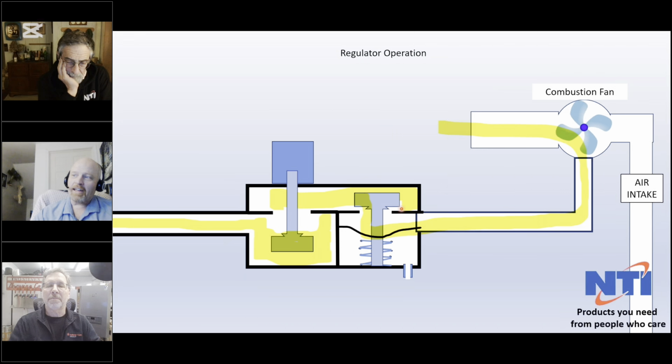Boiler installed in a pool room. This is a tiny bit off topic, but it's kind of pertinent to the conversation. Installed in a pool room, it clogged up the condensate drain after 3 months.